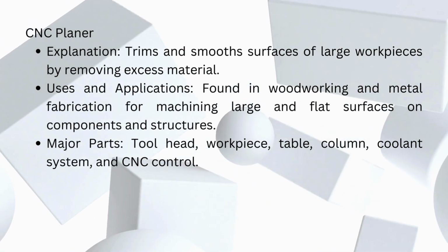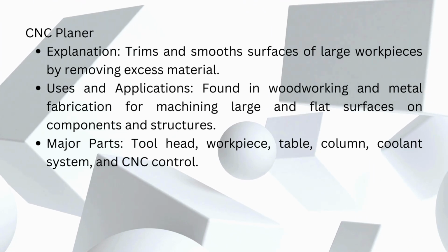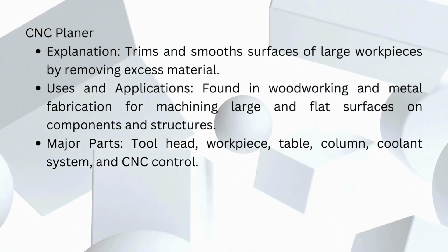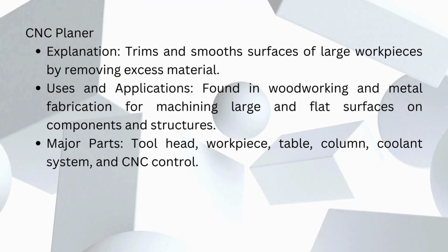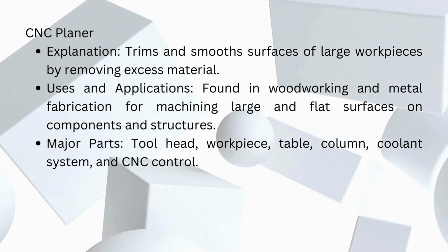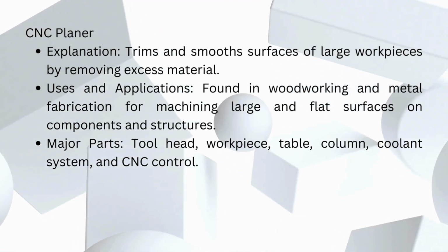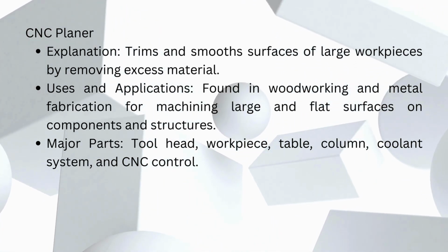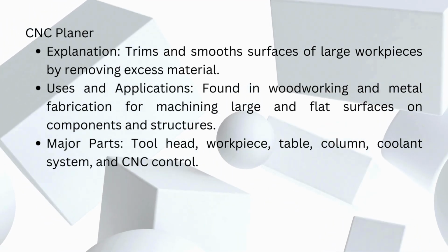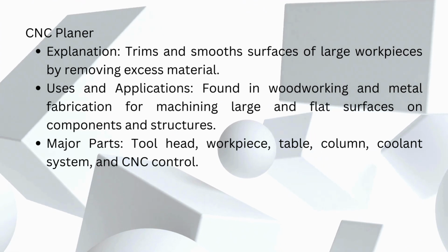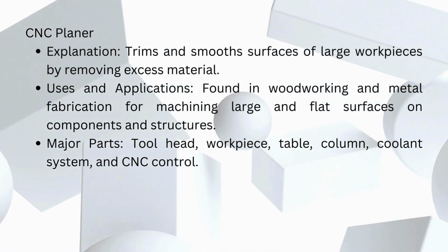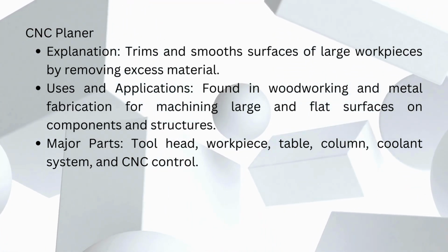CNC planer. Explanation: trims and smooths surfaces of large workpieces by removing excess material. Uses and applications: found in woodworking and metal fabrication for machining large and flat surfaces on components and structures. Major parts: tool head, workpiece, table, column, coolant system, and CNC control.